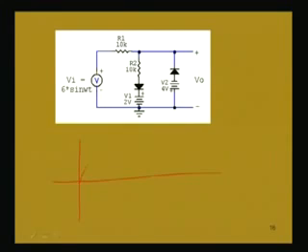That means, if we consider the input voltage waveform Vi, sinusoidal, this is 6 volt. Then from 0 to 2, this is time, suppose 2 is here. So, from 0 to 2 you will not find any of the diodes conducting, V naught and Vi are exactly equal, up to this portion V naught and Vi are equal. This is for Vi greater than 0 and less than 2 volt.